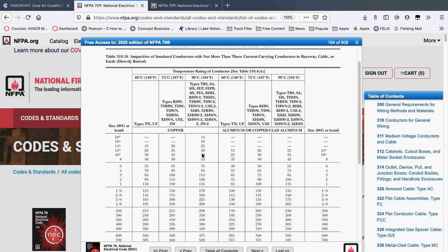Okay, at night, again, we're at 240 volts. In the daytime, I'm hitting 252 as an average, sometimes 254. That's a pretty significant swing. Now, I know the reason for that in my case. Okay, it's the solar panels. But the reality is that can really mess up equipment if everything isn't sized properly.